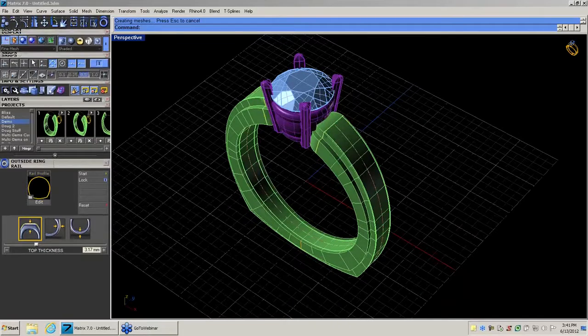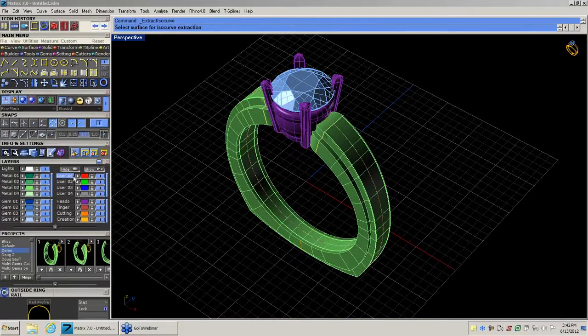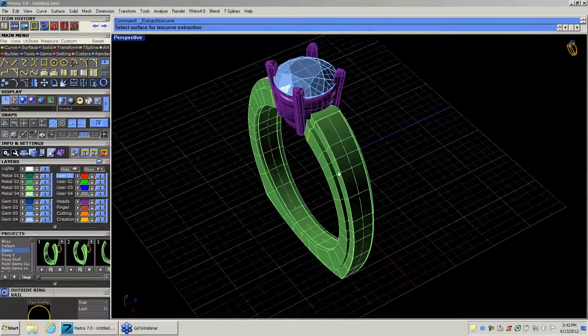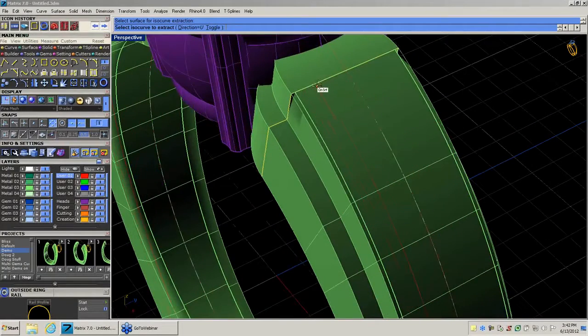The next thing I want to show you here, we're going to come back to our yellow curve menu, and I'm going to click here, and I'm going to come down here to my layer menu, and I'm going to put this onto a red layer, okay? Because I want to come out here and grab a curve out of here, and I want to find the middle of this, and you'll notice as I drive this thing across that it's snapping to different places out here.